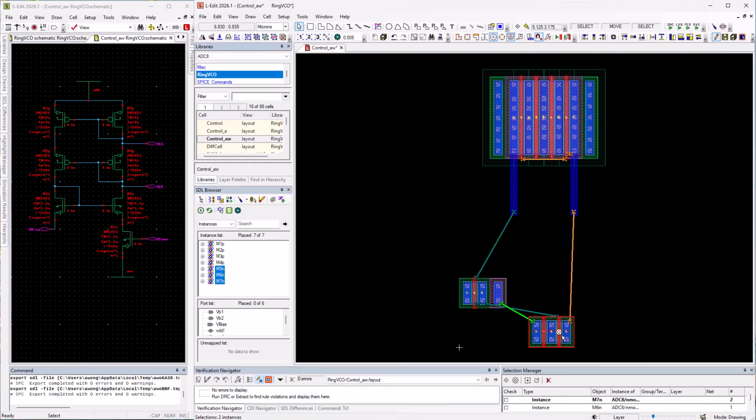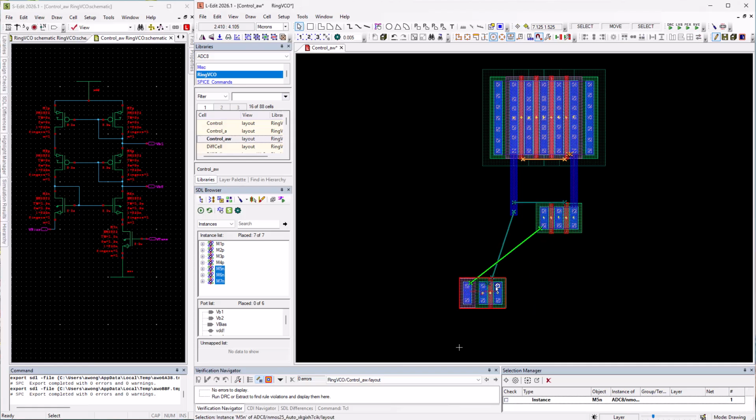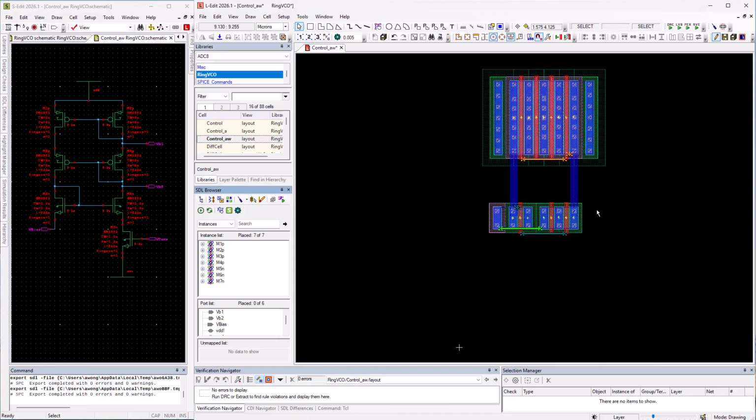And then this, I want to align with this line, and then this, if I rotate, I want to align this with this line, and then these two should be aligned as well. So I'm done with the device placement. The rest is then just to connect the rest of the terminals based on the Flyline. So here, by using the Show Connected Flylines command on groups of devices, it allows me to optimize connections within the groups as well as optimize the connections from group to group.